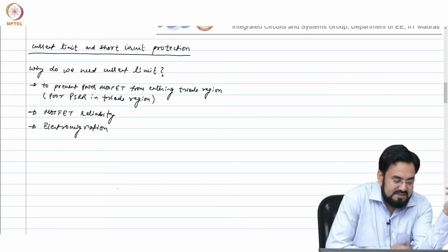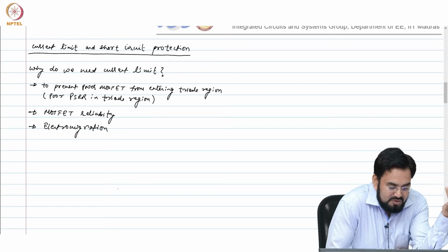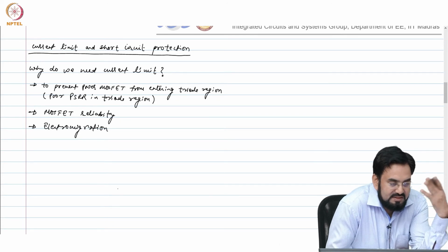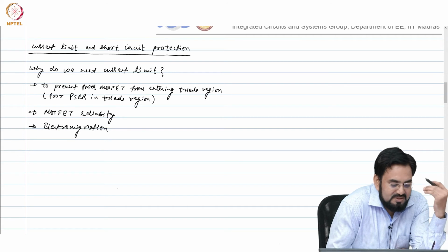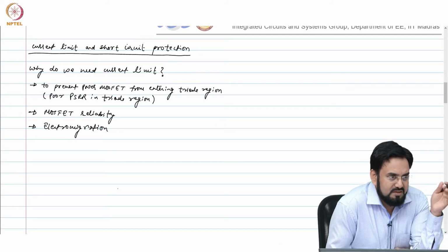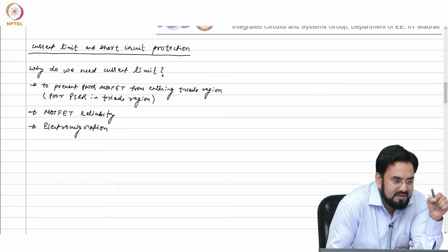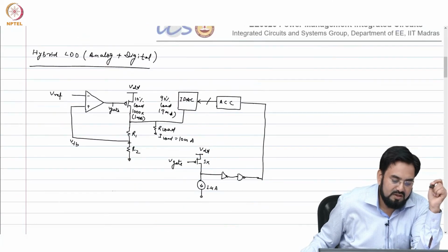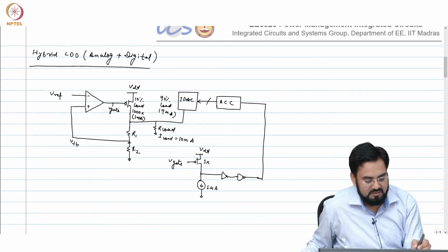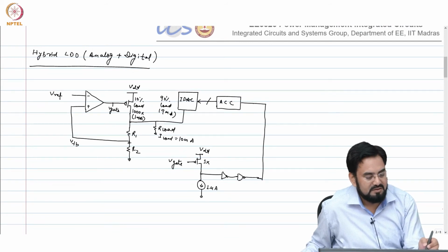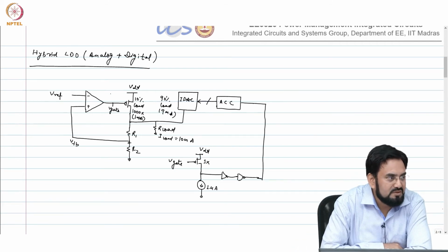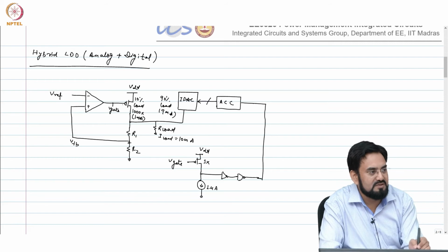The current limit basically is applicable to both short circuit as well as higher current. So when you are increasing the load current and crossing that, that is more like a soft kind of a short circuit, not a hard one. When it is short circuit, you are literally connecting your output to the ground. So when I connect this output to the ground, this will go to 0 and this gate voltage will go towards ground 0. So you are applying the full VGS to the device, right?